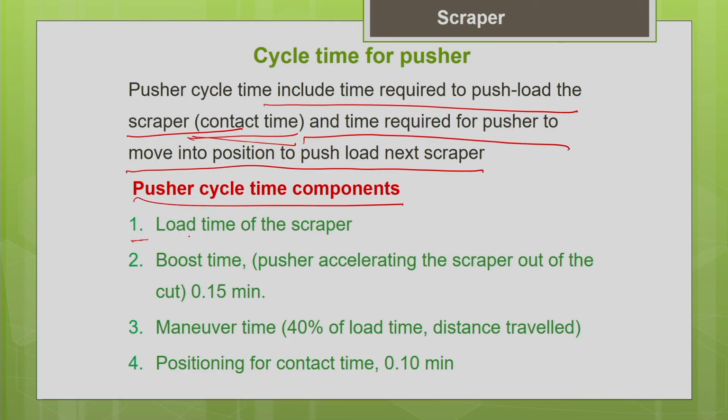One is the loading time of the scraper. And the other one is the boost time. The pusher will accelerate the scraper out of the cut. So that is called the boost time. Pusher accelerating the scraper out of the cut, say approximately 0.15 minute can be taken as the boost time.